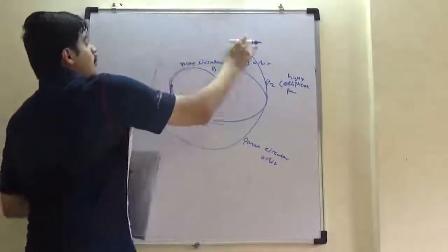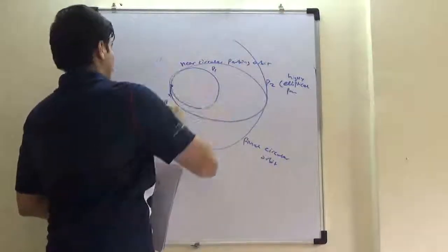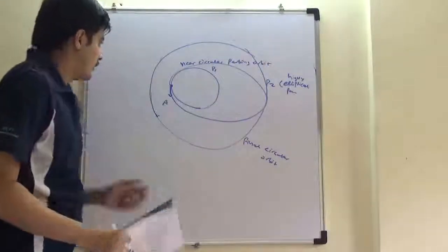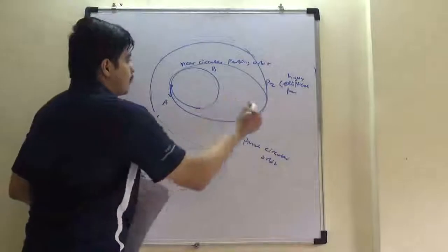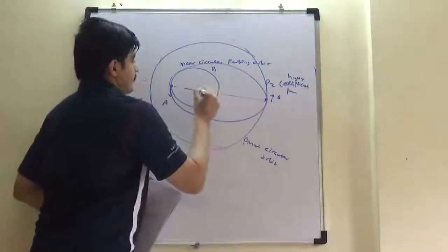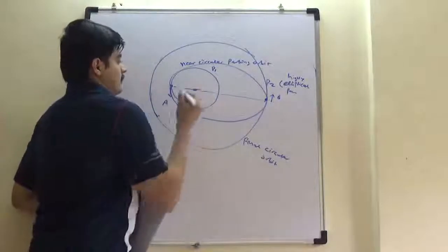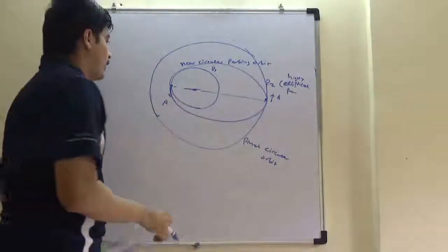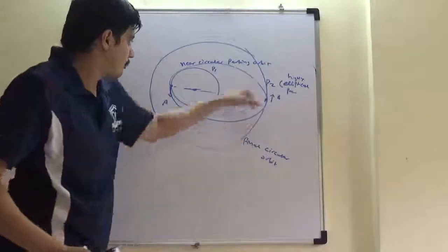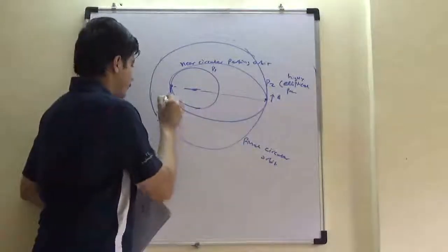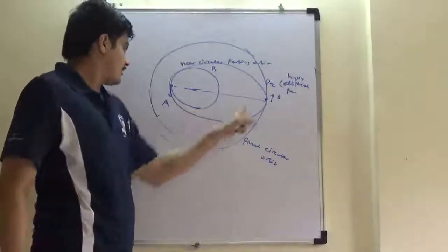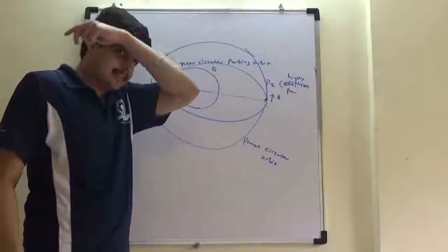This is our most optimistic strategy to minimize the fuel consumption, right? What does that mean? Moment you came to point A, you want to change the orbit from circular to elliptical, which means the velocity properties here have to change so that the new properties will make sure it forms this.